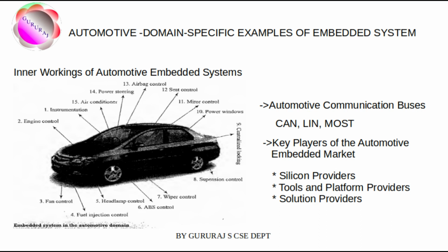The MOST bus specification defines the physical layer as well as the application layer, network layer and media access control. The MOST bus is an optical fiber cable connected between an electrical optical converter, EOC, and an optical electrical converter, OEC, which would translate into the optical cable MOST bus.